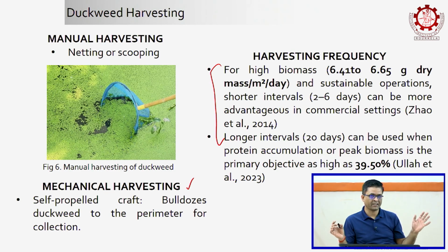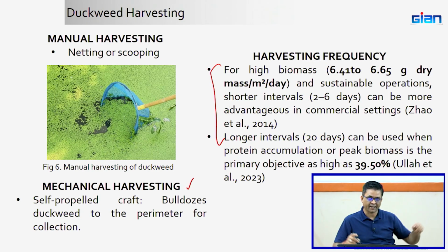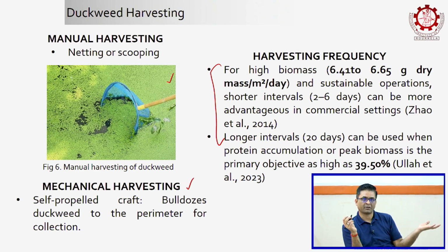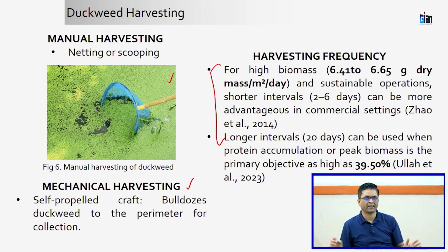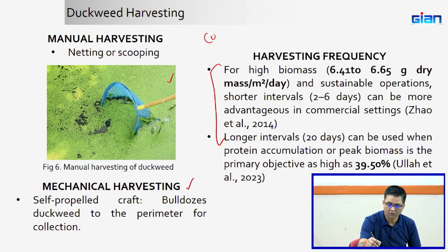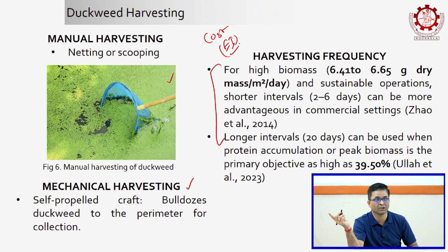Did you get the purpose right here? So if you have a large area, you are continuously getting biomass. Whereas if you are using the wastewater treatment system, what you are getting continuously is the sludge, which has to be disposed at some point, some way or the other. Then again, wherever you are disposing, you have aluminum and all those chemicals which are going in. So with this, you are not adding any nutrient or any input chemicals, because when you add any chemical, flocculating agent or so, there is also a cost and environmental impact of producing those chemicals, which is also associated with life cycle assessment.